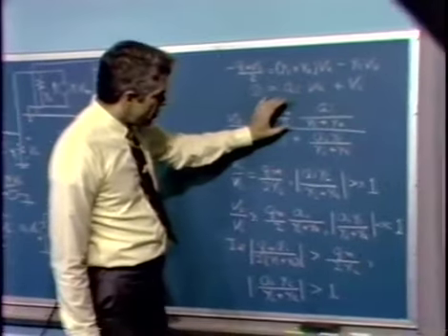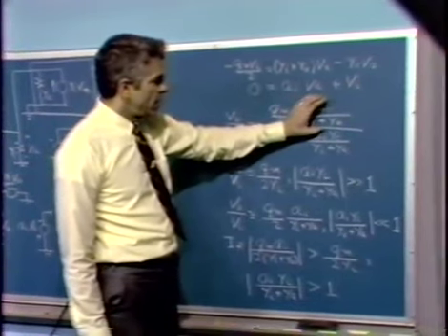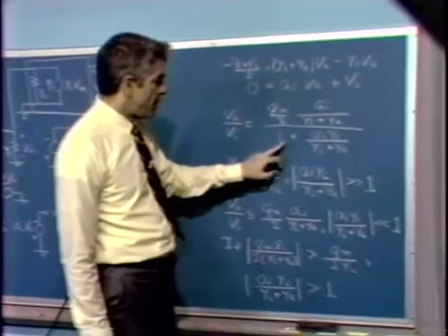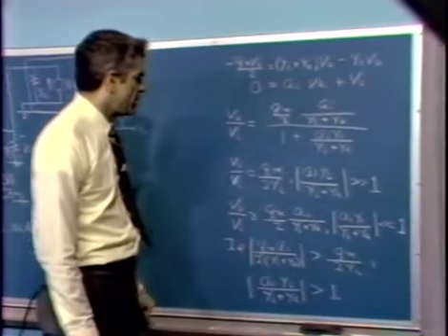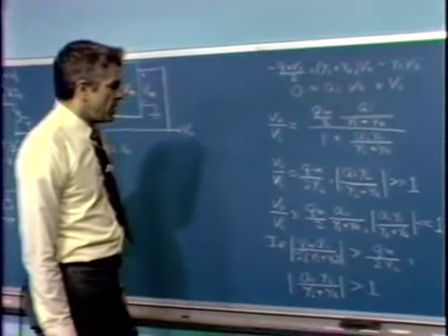So we have the numerator of this expression being the gain the amplifier would have if the minor loop were disabled but its loading were considered. The denominator of this expression is 1 minus the loop transmission of the minor loop. And again, there's the familiar limiting cases.